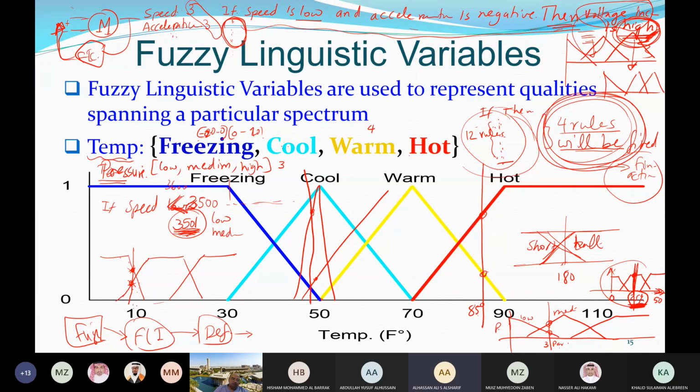So when it reaches 90, 91, 92, for, let's say, 10 minutes, it can tolerate it, does not trip the motor. But after 10 minutes, it can take an action to trip, for example, the circuit breaker connected to the motor. Can I add this without adding a clock or a timer in the fuzzy logic?